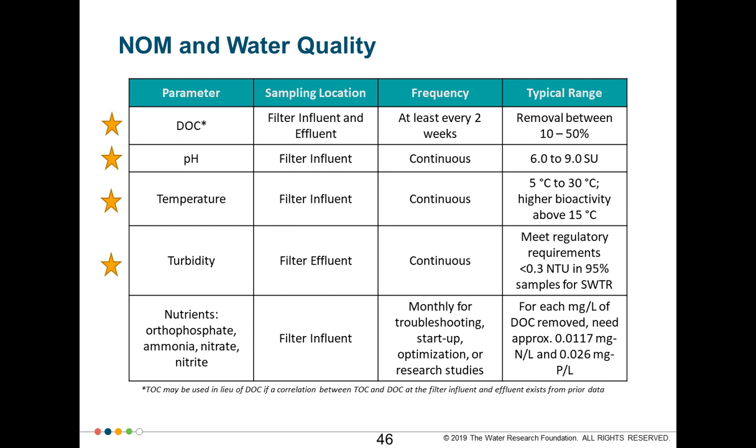For organic carbon and water quality monitoring, we highly recommend including DOC. A lot of facilities look at TOC. If they do characterize organic carbon, many facilities use TOC, and we recommend looking at DOC because the dissolved fraction of organic carbon is what is used by bacteria for biological processes, as opposed to removal of particulates that can happen in the filtration process, which you would capture with TOC. So would definitely recommend including either both of those or just DOC.